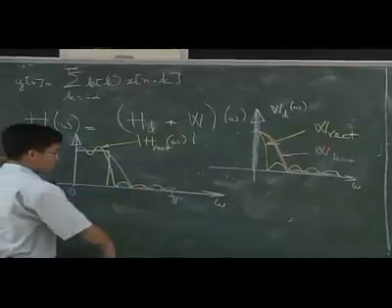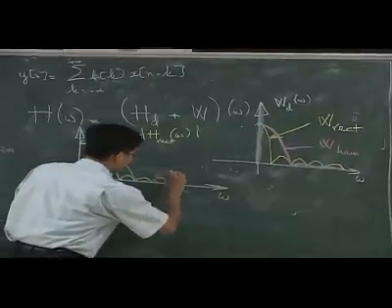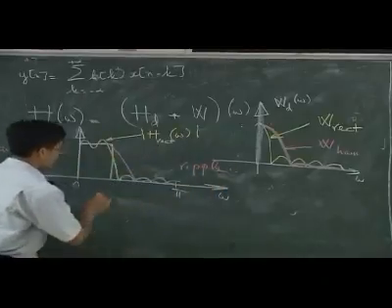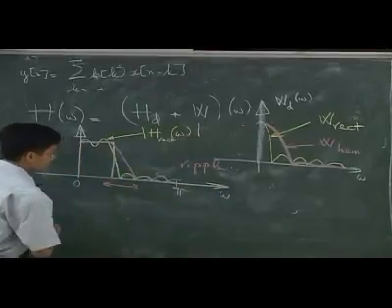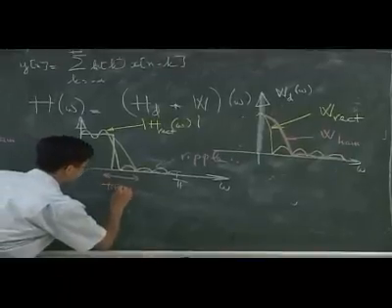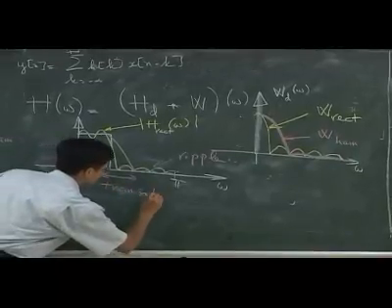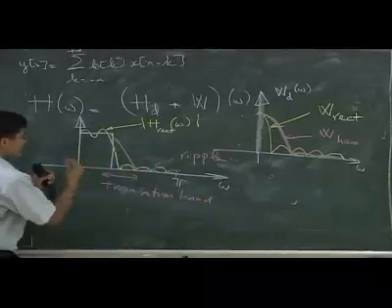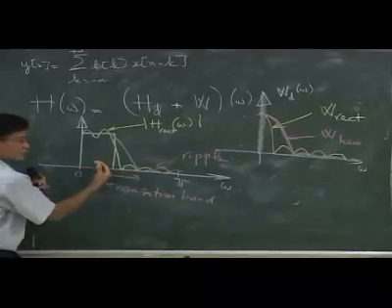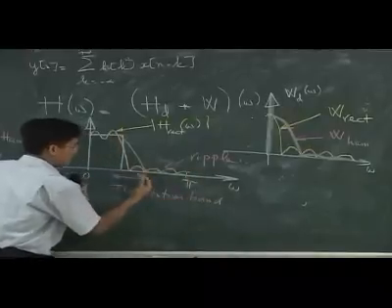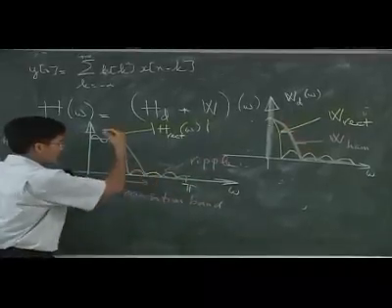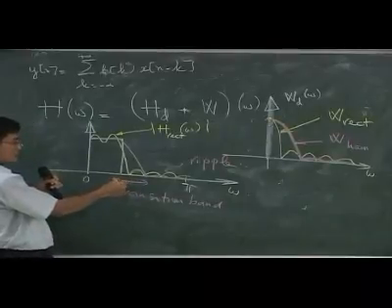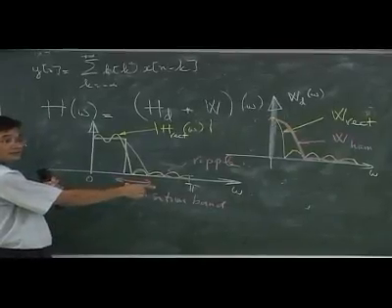Right? You have this thing here, what people call a ripple, and this thing here, people call the transition band. Because here I let things go through. Here I'm going to kill things. But in here, that's where you can have a transition band. And the Hamming simply makes the transition band wider.